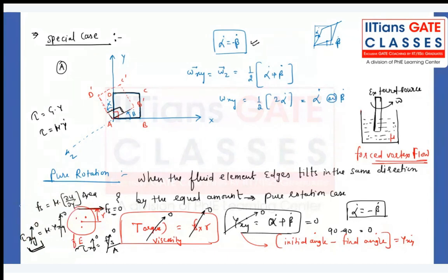Yes, for a static fluid, it will be zero. But that depends on whether the static fluid has been driven by the plate or not. If you are not giving any velocity to the plate, just what we discussed, simple Couette flow, then straight away that is zero. No viscous force, no drag force will be there on a fluid element. In a static fluid, there cannot be any shear force. Remember that. Now, is it done, all of you? All of you have noted down?